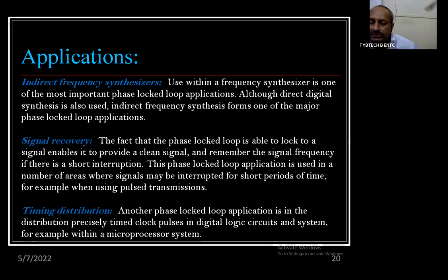So instead of using different circuitry or crystals for generating the clock signals differently, you can use a single crystal, and from that you can make multiple timers, that is 10 millisecond, 20 millisecond, and 30 millisecond like this. And you can give these as inputs to the different circuitry in the same application.